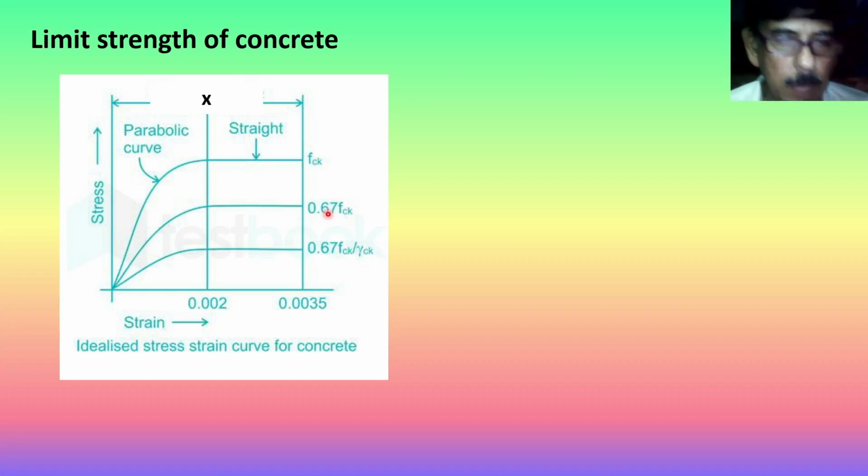So this size is much smaller than the sizes that will be encountered in the field. This is called the size effect. Lower size will give you higher strength. And because the cube is put under two steel platens and tested, it shows more strength than actual. So this tested strength Fck is reduced by 2/3, and this is, you can say, the available strength